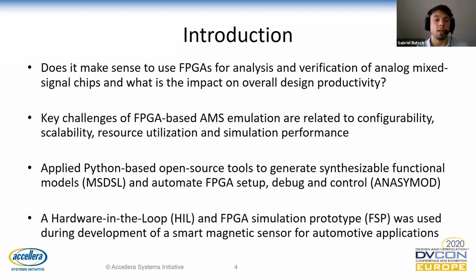Another important aspect is resource utilization. And since we're targeting medium to small sized FPGAs, this is more critical compared to, let's say, a proprietary emulation platform. And typically, there's a trade-off involved between the simulation throughput that you could achieve and the resource utilization that you need in order to represent a certain functionality on the FPGA.